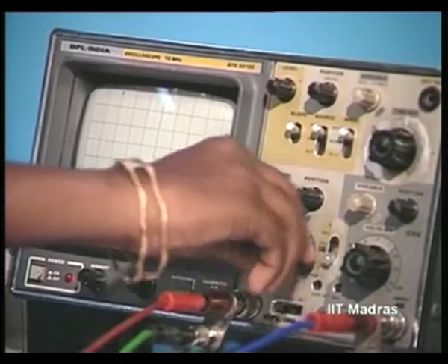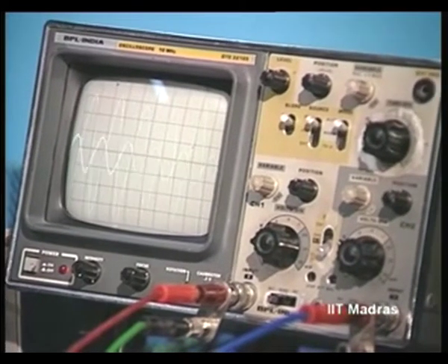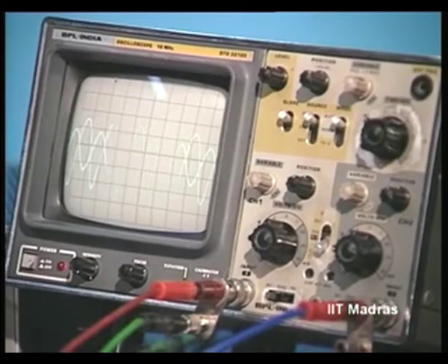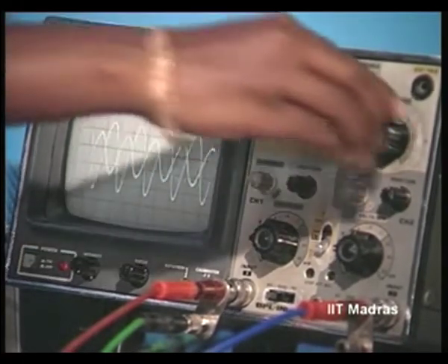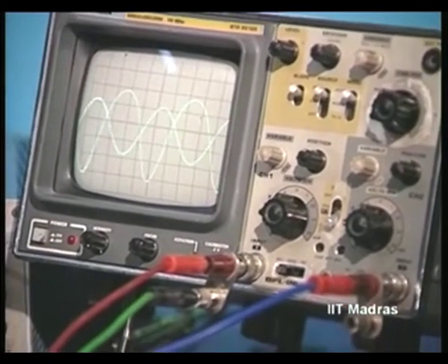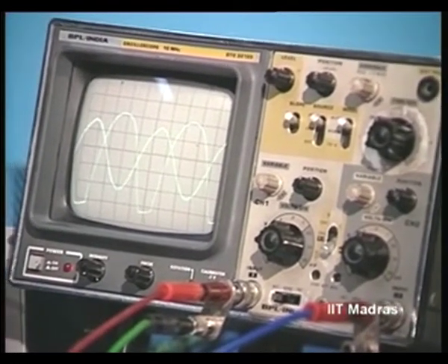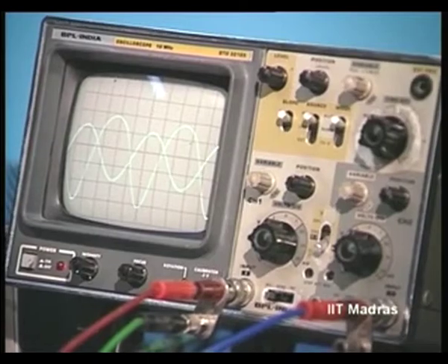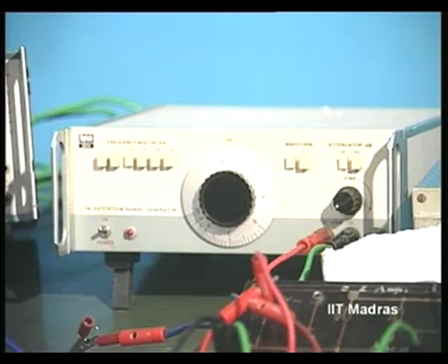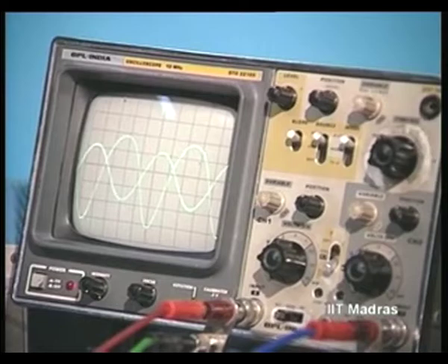This is the exponential waveform, right? Because the current is exponentially related to the input voltage, we have the top portion broadening and the bottom portion narrowing. Now please increase the signal level slowly. Just decrease it a little bit. You can see the lower portion going to saturation, and the upper portion corresponds to cutoff. So, that is the signal limit.